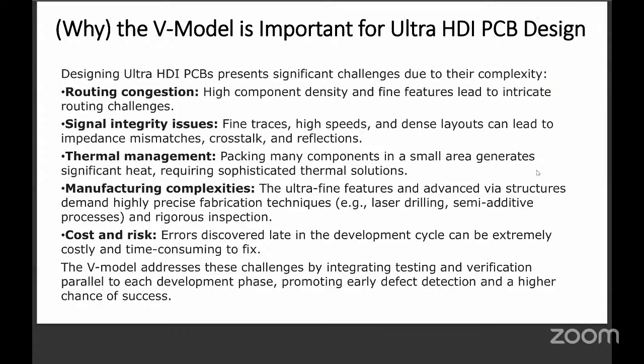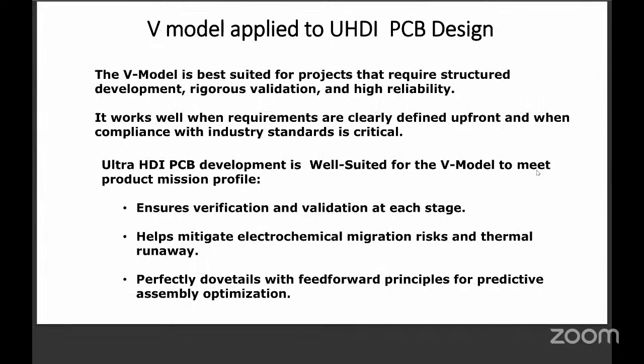See, there is a groove, and on the groove nothing should come. That's a valid statement. But the groove is no longer in mils; it is in microns. Number one. Number two, even in silicon, when they do dicing, they leave some gap for the wheel to move. But in that region they put some coupons so that the area is not wasted. That's the only way people save. But one thing is, here we cannot pack as many PCBs in a panel as possible. The number of PCBs per panel is going to be less.